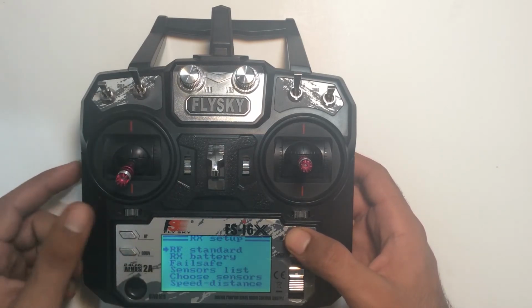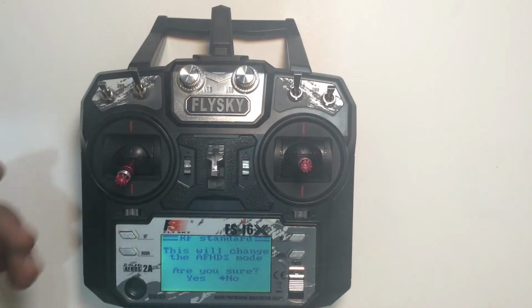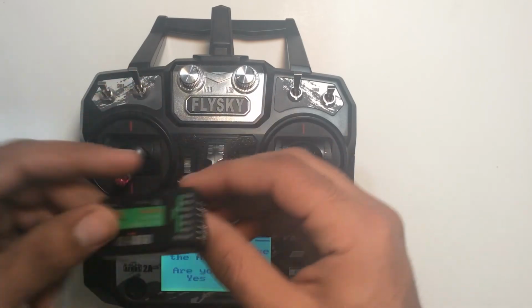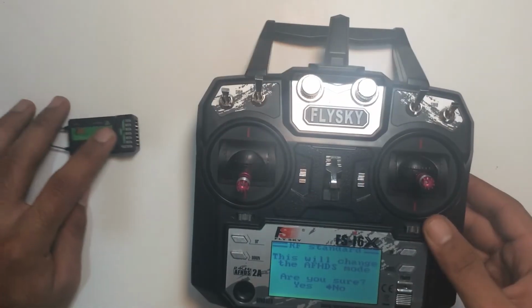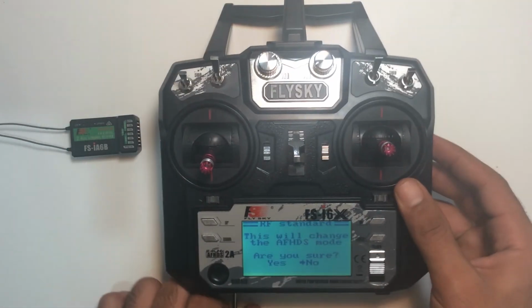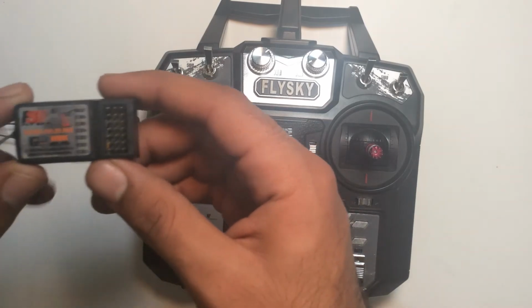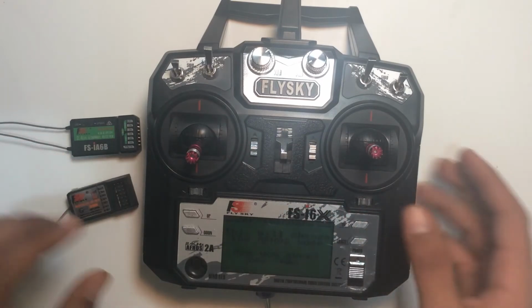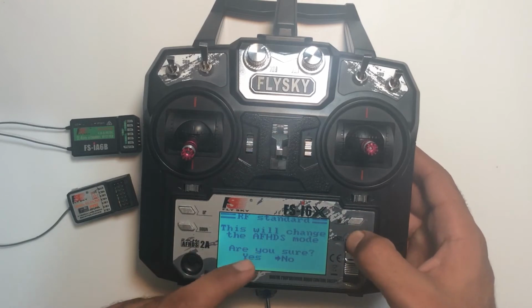The first one is the RF standard, which means on which protocol you want your receiver to work. For example, I'm just using this receiver, the Flysky FS-iA6B, which works on the protocol of AFHDS2A. You also have some receivers which are working on the protocol of AFHDS. For example, I have this receiver which works on the protocol of AFHDS. So here we have to mention which protocol you want to use.